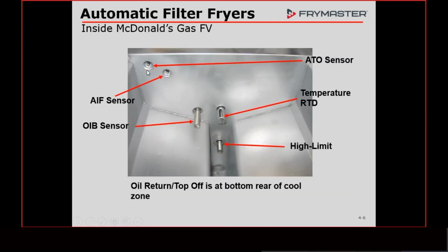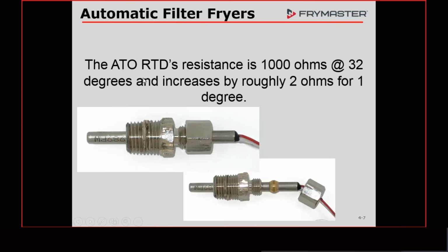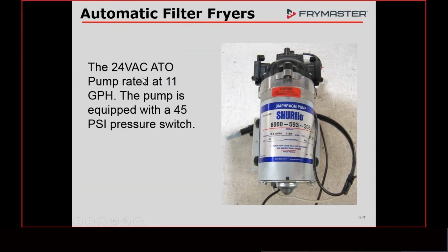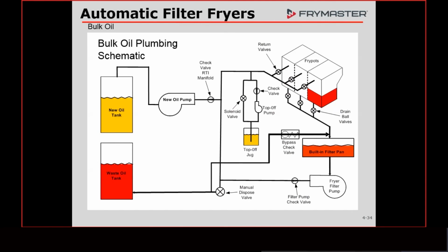Right now, you probably are thinking, yeah, we need to make sure that probe is clean. Good, because that is probably the number one thing. That gets jammed up with debris because all that stuff floats to the top and gets in there. Then that oil will pass right by instead of going into that socket, because it doesn't have enough oil on the surface of that probe. So that would be one thing that you want to look at if the call is that the fryer is filling up too much or topping off too much, which is usually how they phrase it.